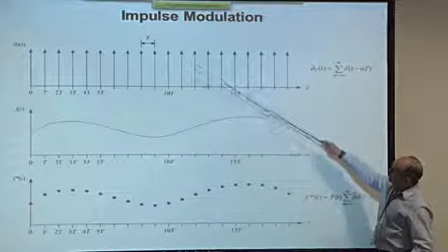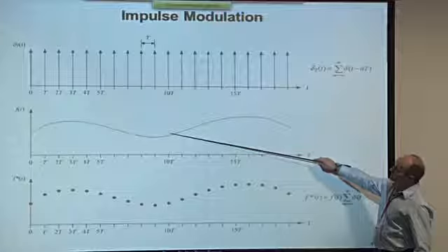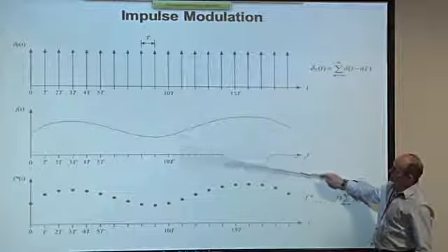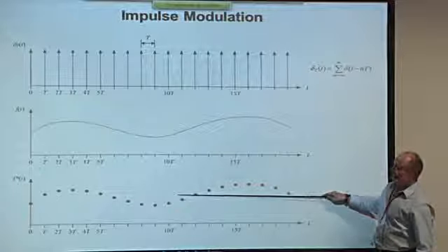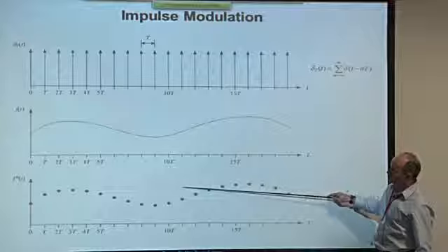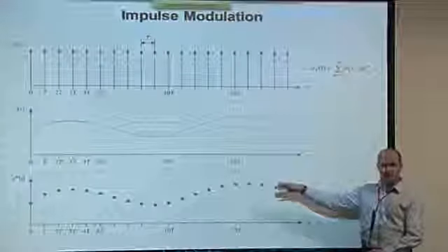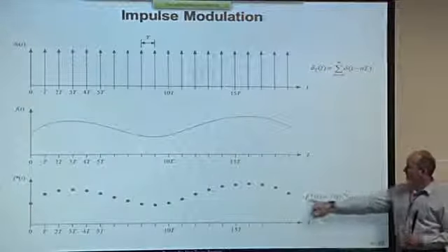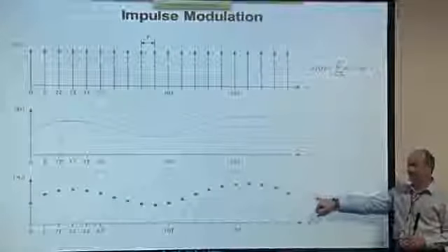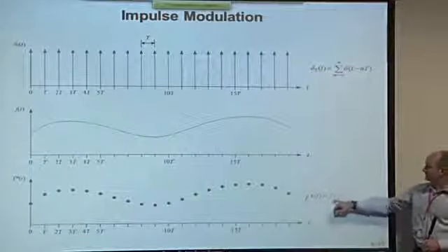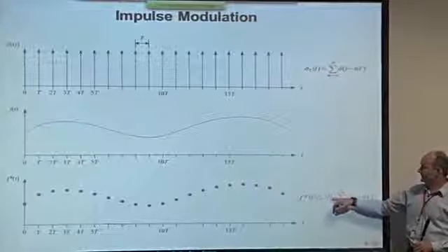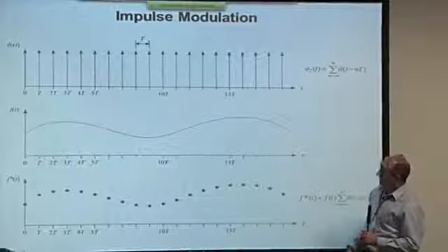Now, when we apply this to a continuous function of time, of course, we can use the screening property at each instant to give us a number, the number corresponding to the value of the continuous function at the instant at which it was sampled, and we end up with a list of numbers. Sometimes we denote that list by the symbol star. f star of t, the sampled signal, where the original was f of t, is equal to the combination of the infinite series of delta functions with that function of time.